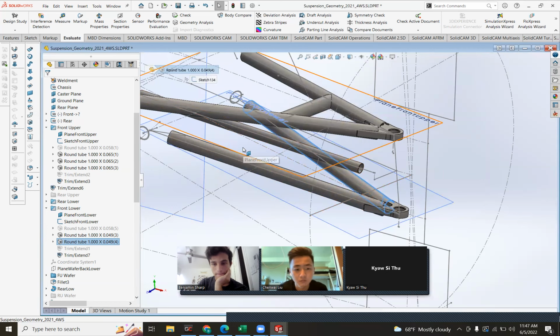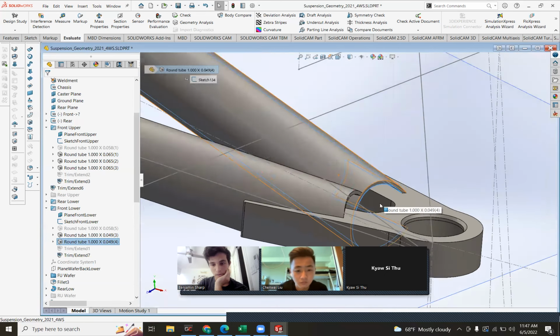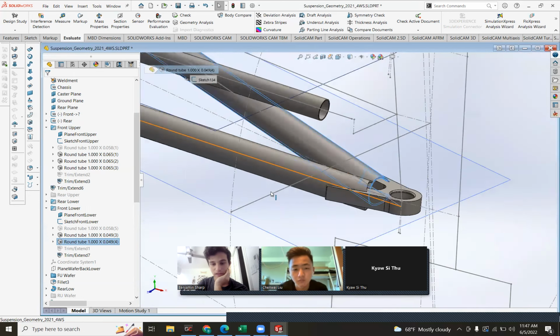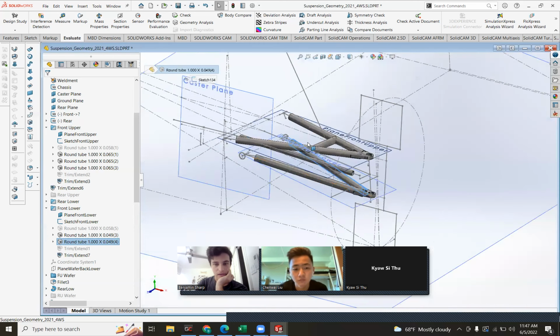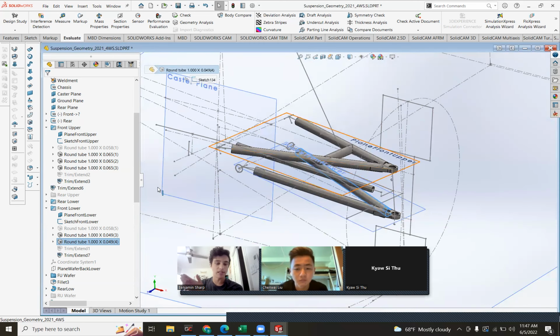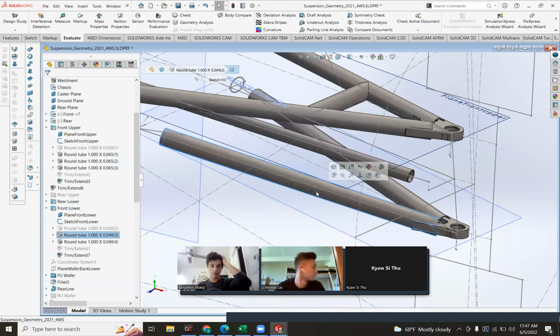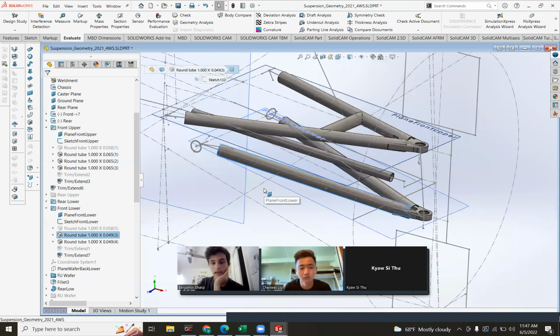We can probably check this by measuring in this gap if we have a spare and we can fit some calipers in there. But it's also up to you guys what you want these thicknesses to be. I would recommend for non-load bearing arms that you make them either thinner, so either 0.35, or make them a 3/4 inch diameter. Because we want to save weight on the arms, they're pretty heavy. And when they're non-load bearing, they don't need to be that strong.